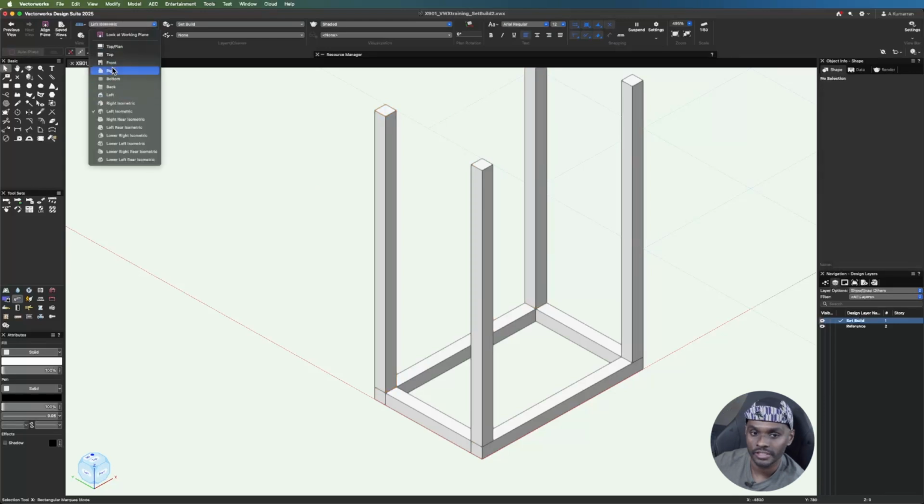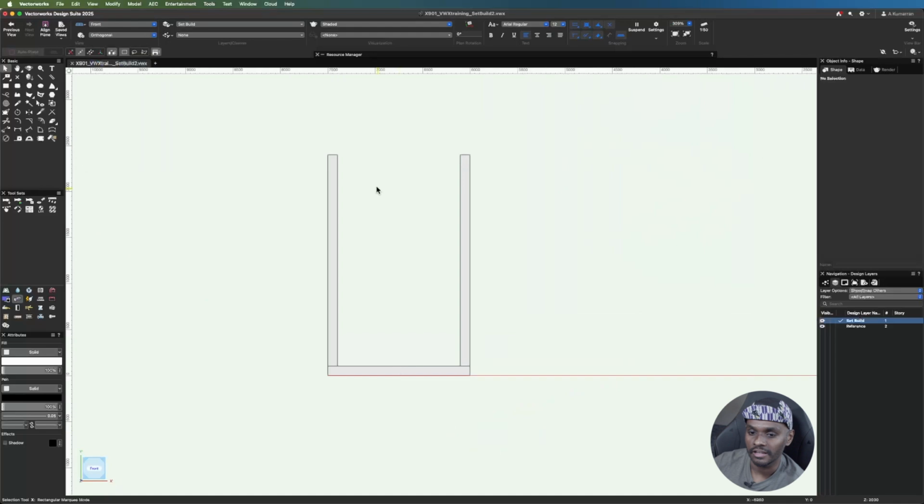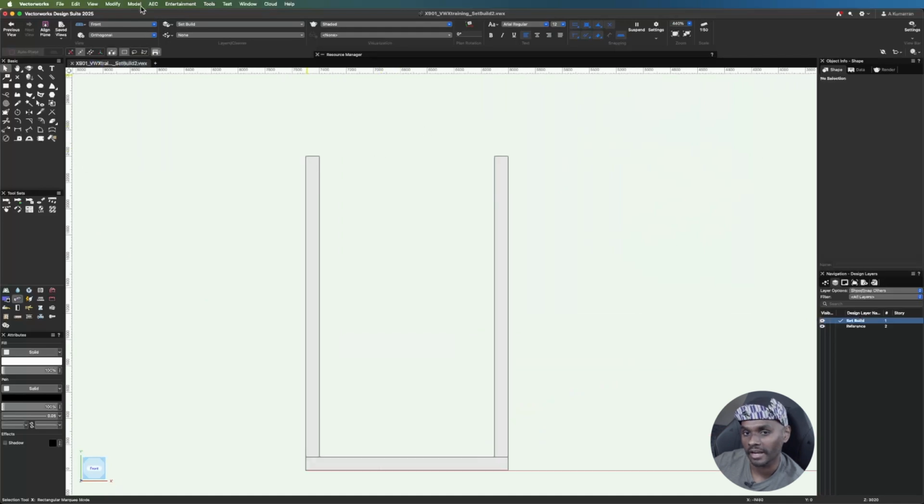So from here, I want to work on the top half of the bracing frame. So I'm going to shift over to the front view, and if I look at my designer's concept, he wanted an 8-degree slope from here to here. So I might not be able to promise him exactly 8 degrees, but I will try to get as close to it as possible. So using a line tool, I'm going to start from here, and I'm just going to draw out in this direction, and I'll tap once on my keyboard to get to the length, and I'll tap again to get to the angle.